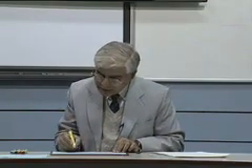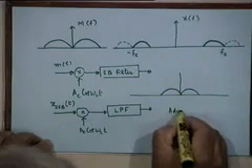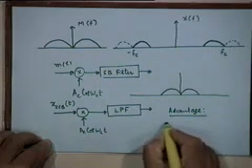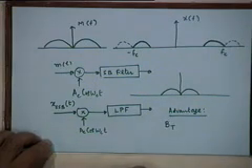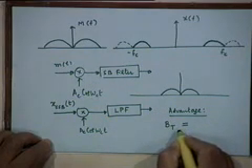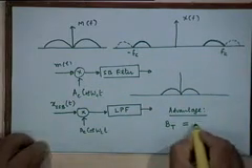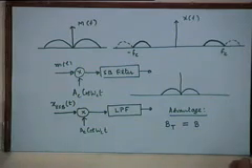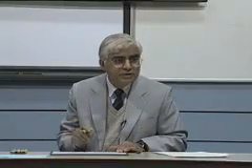Now so far so good, but before I come to that, what are the advantages that we mentioned of doing this? The main advantage is power bandwidth efficiency. Your transmission bandwidth B sub t is now not equal to 2B, which was the case for the two previous modulations we discussed, but simply equal to B. So in the same bandwidth you can transmit two messages, rather than in the 2B around fc a single message.